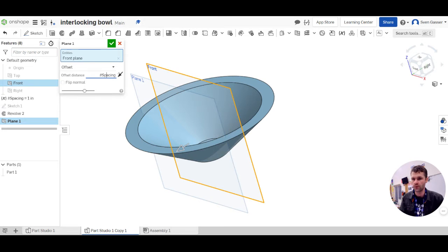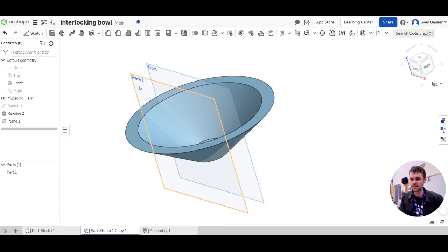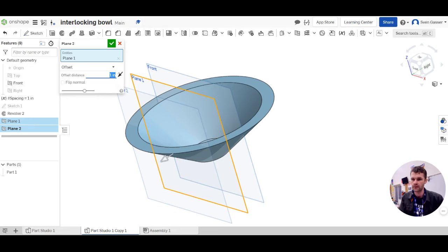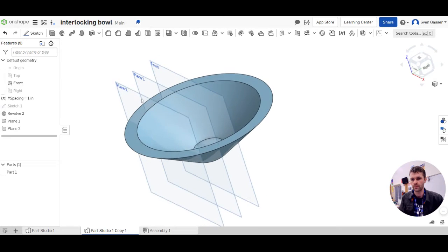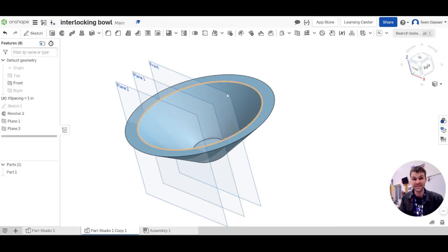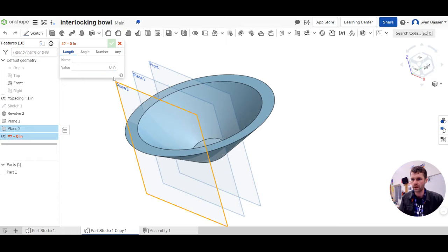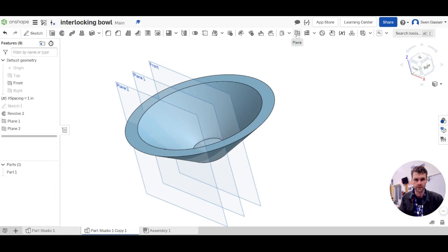So it's important when you first do that, you're just going to type the first letter, and usually it's going to pop up there. And look at that, it says spacing. I just click on that, fills in the gap, hashtag spacing, and that's going to create that surface at just the right spot. And then I'm going to repeat that again, clicking on that new surface though now. So now it's spacing again, and now I got my third layer, and that gap there between the two is the same, and I'm going to keep repeating that until I'm, oops, I click on the wrong thing? I clicked on the wrong thing.